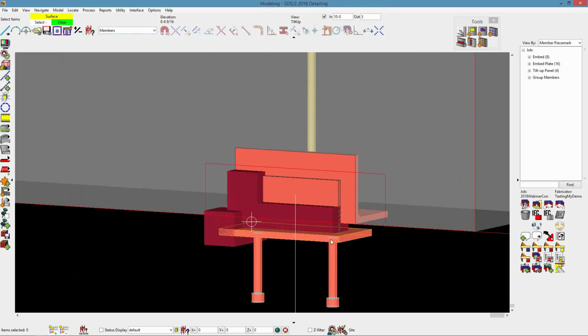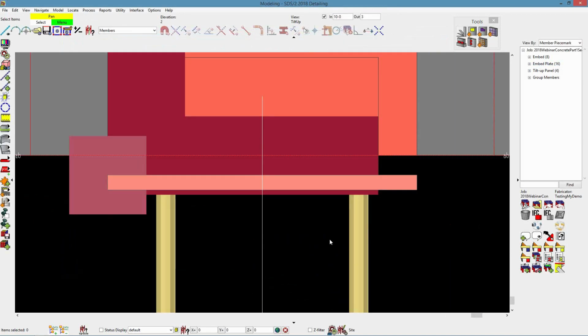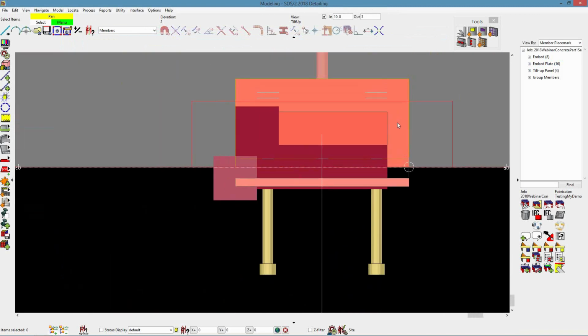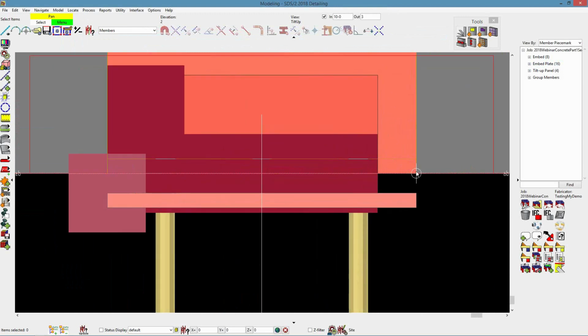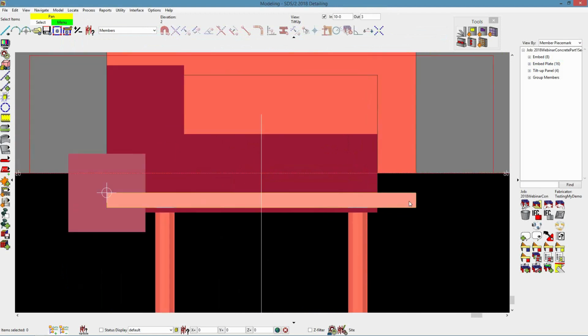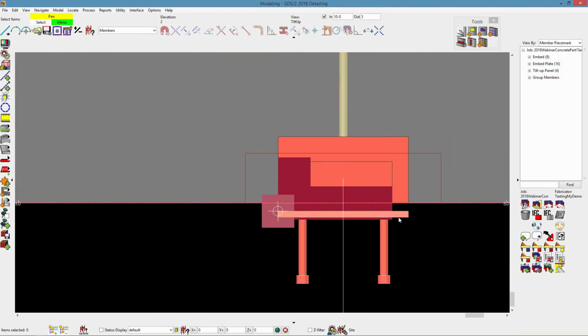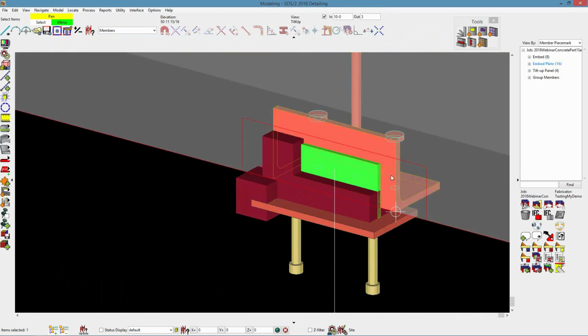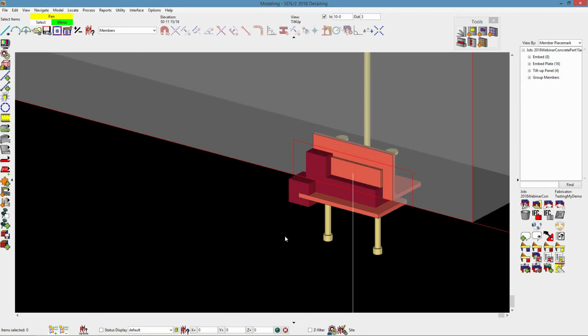So if I come in here and surface, you can see that from this embed plate for inside the tilt-up panel, the panel embed, it's going to be 1/2 inch down is where I have my footing embed, and that was when we're adding it in. I had the setback at the very top of the option there, so that's what that's going to control. But once they're placed in, they are just now each individual miscellaneous members.